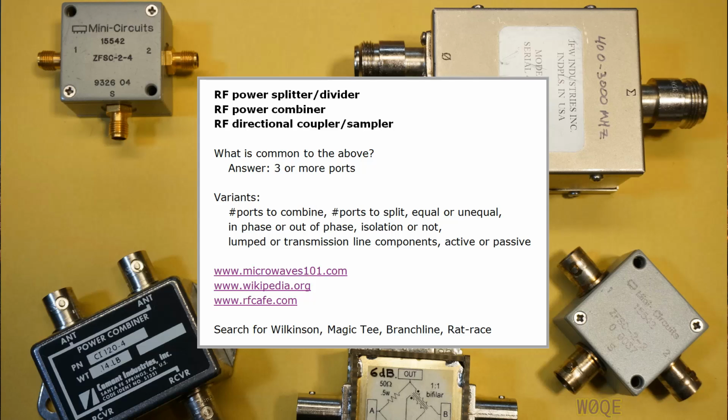You can split a signal into two equal signals, but you can also split a signal into a signal that's twice as big as another signal. And that's done quite often in the case of a directional coupler. You don't want to take very much of the energy to couple to the output port, the coupling port that's used to monitor the signal. So in that case, you might only look at 1% or even 0.1% of the signal.